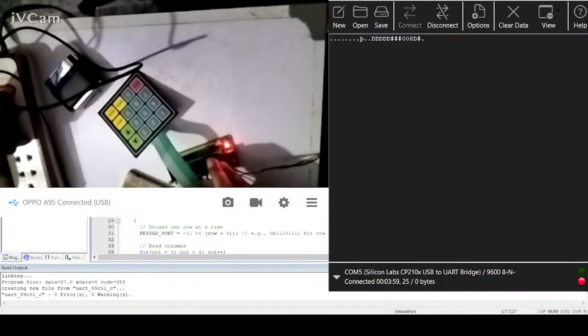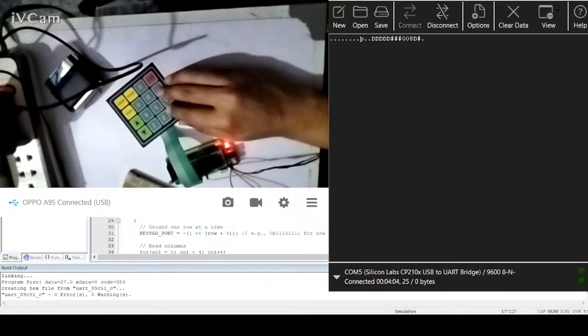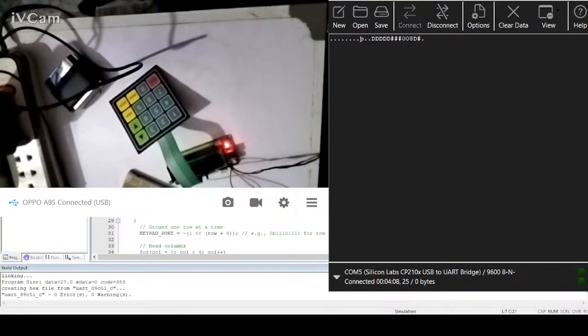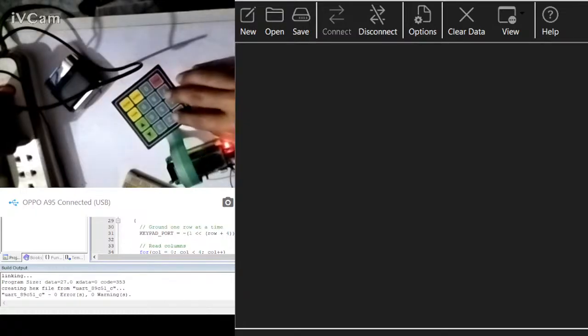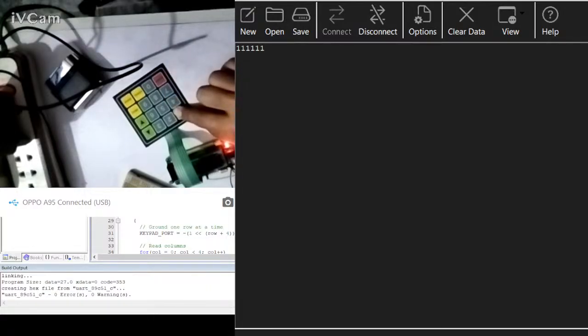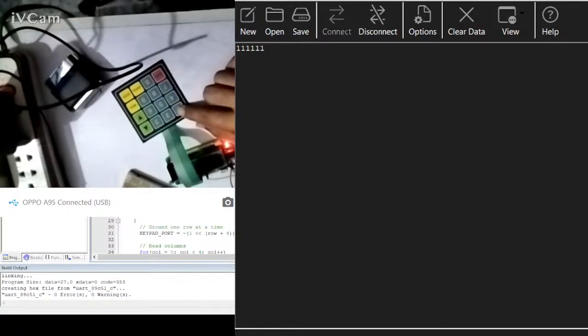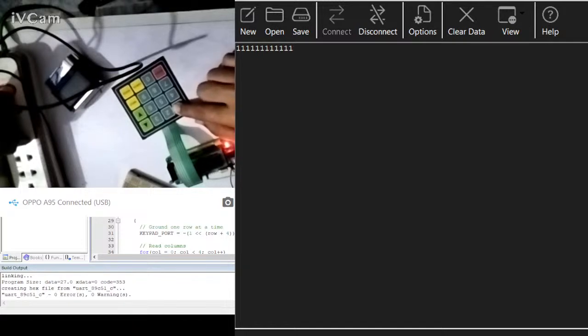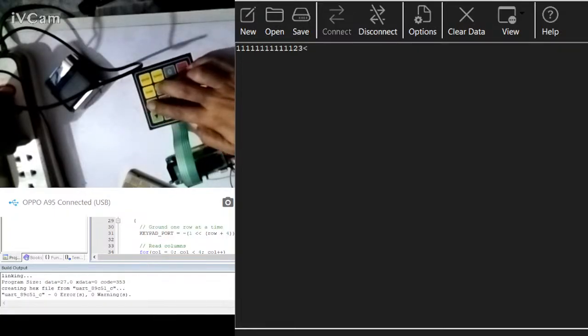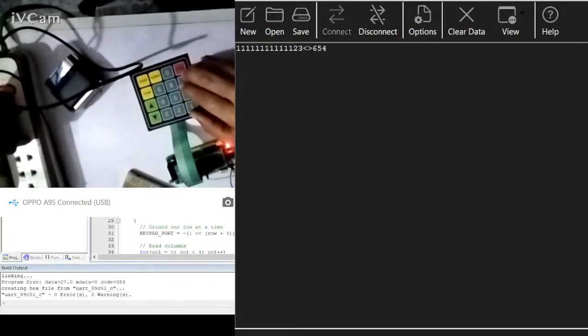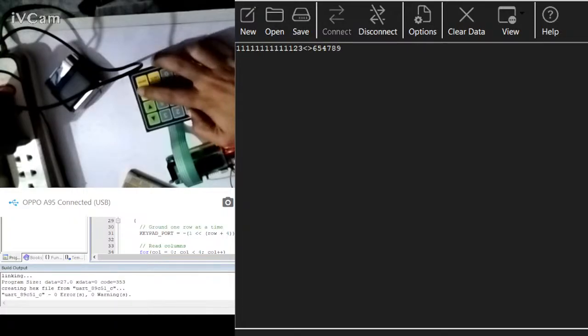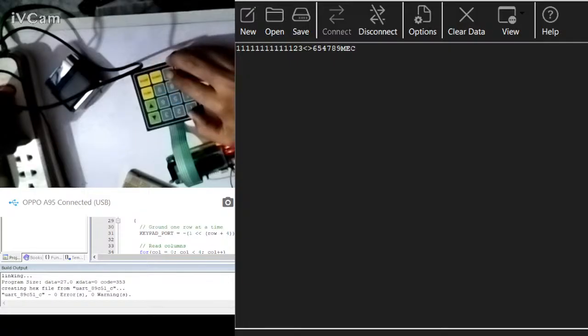So after placing the IC, while it's on, I have to reset the button, reset the controller. Let me now increase the size of the screen and clear it up. So one goes over here. When I keep it pressed, the debouncing is working, so nothing is happening. And as many times as I press this, it's just going to recognize the whole thing as one single press. 1, 2, 3, arrow, arrow back, 6, 5, 4, 7, 8, 9, menu, enter, cancel, 0, and S.